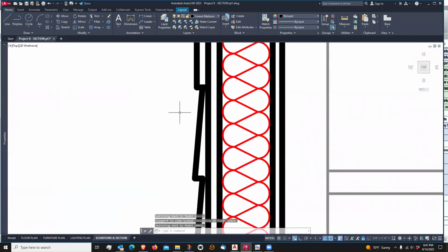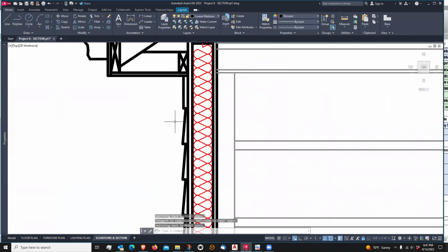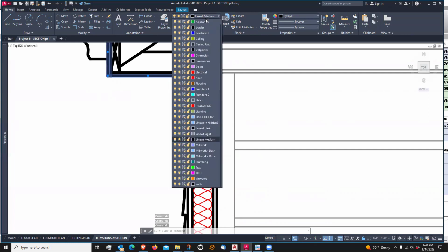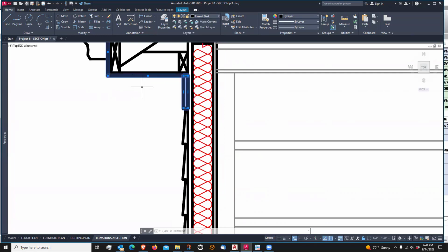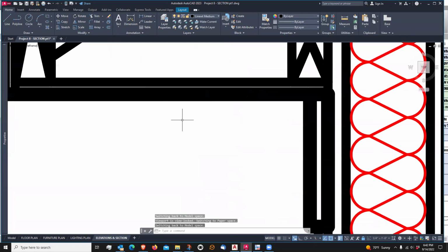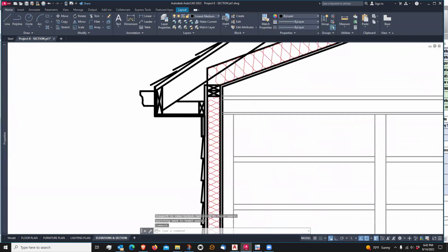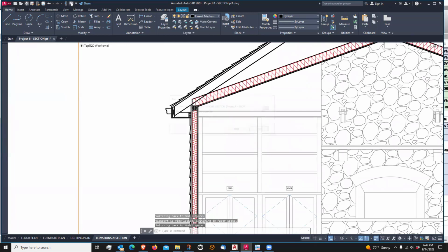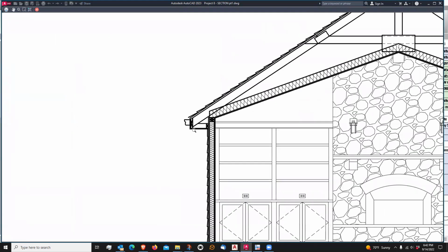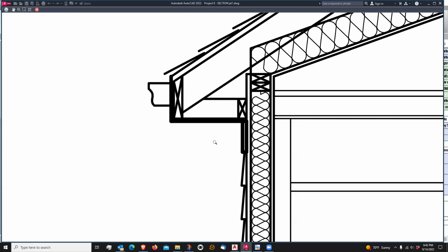Right here, this is the heavy line weight and that's a medium line weight. I can barely see the difference between the two. But in any case, I do want to change these perimeter lines to line weight heavy or dark. Now see, that to me is just really muddy looking, but let's see what it looks like when I plot this. Well, it comes out a little better.